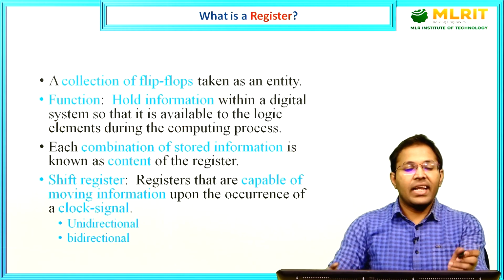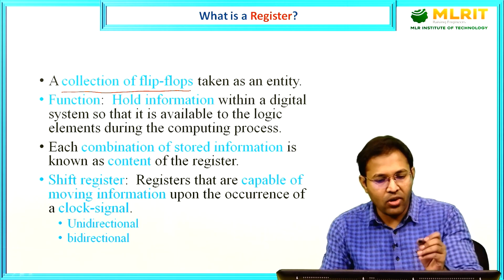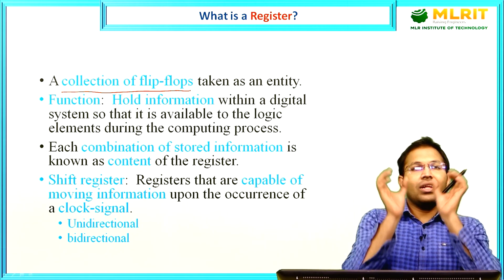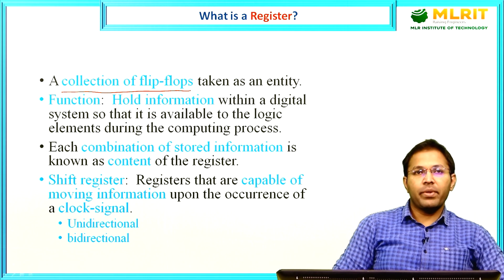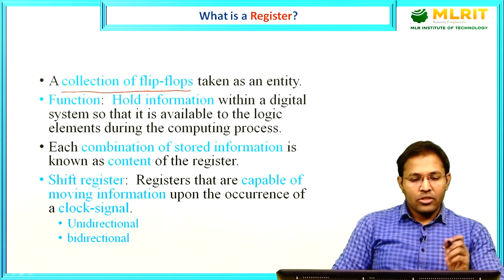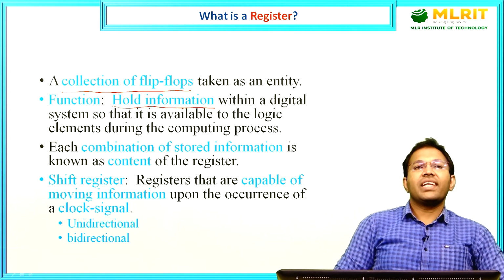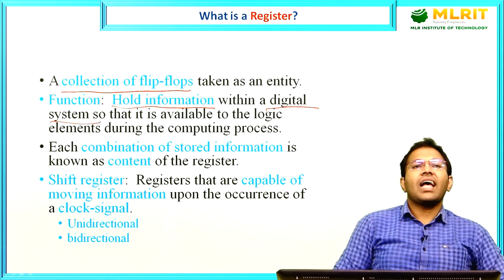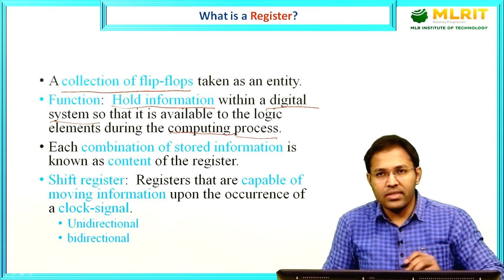Register is simply a collection of flip-flops taken together as a single entity. For example, 4 flip-flops together form a 4-bit register. 8 flip-flops together form an 8-bit register. Okay, so what is the function? It is to store information or hold information within a digital system so that it is available to the logic elements during the computing process.